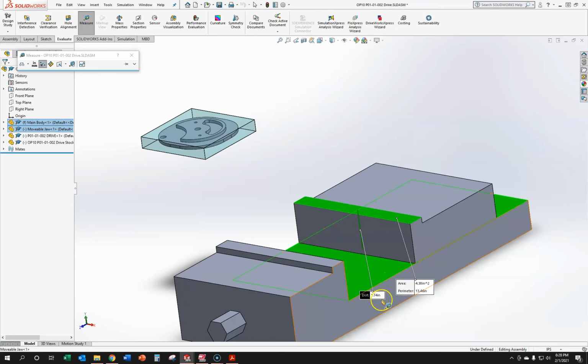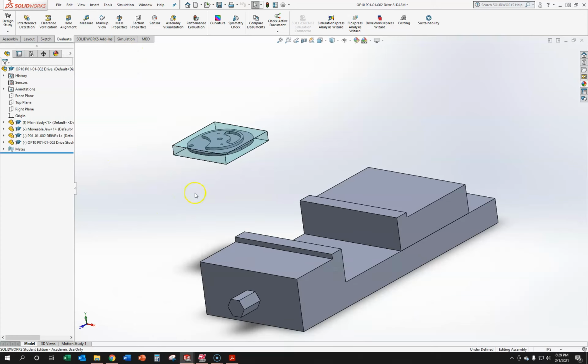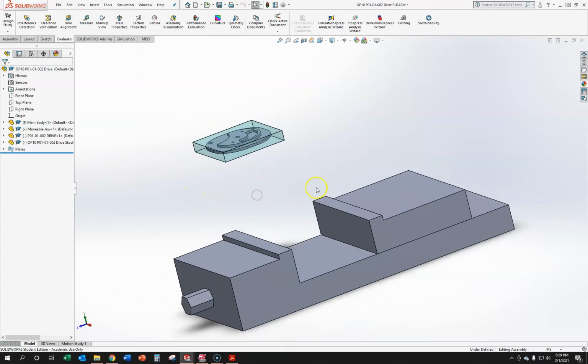Actually, it'd be more than that, right? Because if we have a 1.5 inch parallel, and then we have this sunk in onto it, that means we'd have about 1/4 of an inch in there, which is roughly what we want. I actually think we may need to go to 1 5/8 parallel in this case to get it to work out properly. In order to deal with that, why don't we make the parallel first, and then we'll come back. So I think we're going to need 1 5/8.